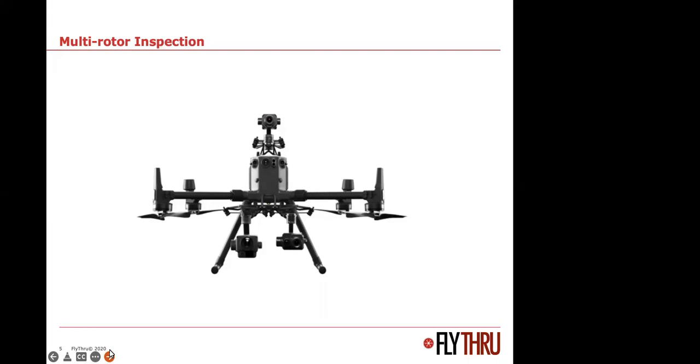I think I mentioned before that when we were flying the original drones with 3, 4, 5, 6 minutes with a 12 megapixel camera. This, as a norm, carries a 42 megapixel camera and will stay in the air in reasonably stable conditions, I'm thinking about wind, for around about 40 to 45 minutes with those payloads on board. And with a LiDAR system, a laser system that we carry as well, about 35 minutes.